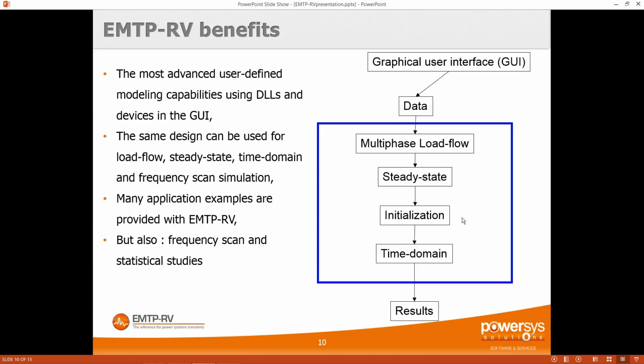The memory usage would be terrible. So for that, you have to set scope before running the simulation. For that, two options. You can double click on a device, and there is a tab named Scope, where you have a list of signals that you can choose to scope. Or we have a meter library, where you can find voltage scope, current scope, sequence voltage or current scope, power, etc. And you can connect this scope directly on the design like you would do on your network. It's really a software in the loop.